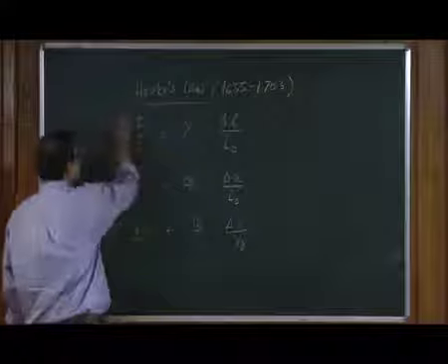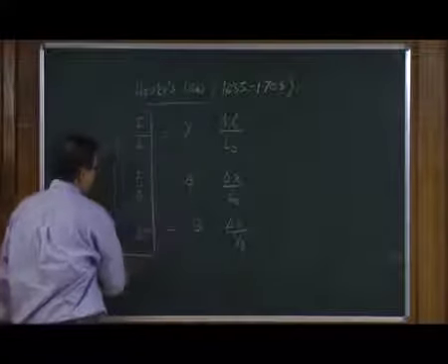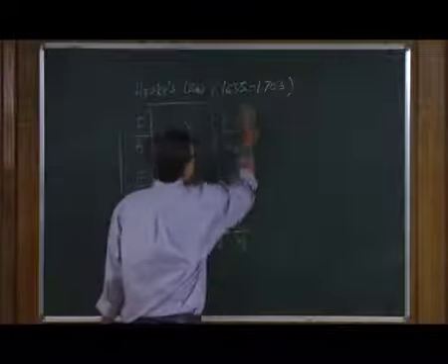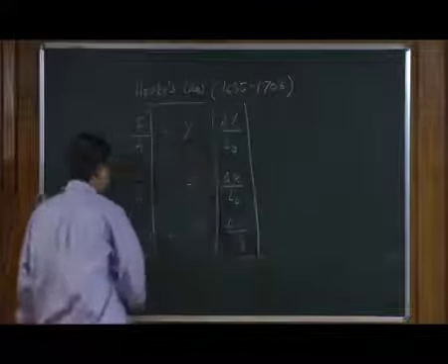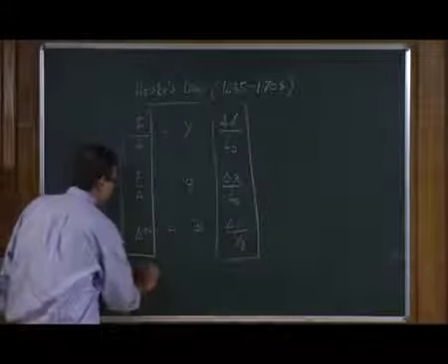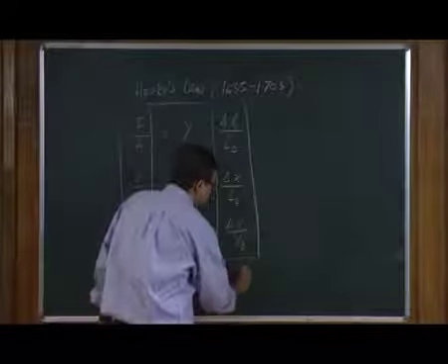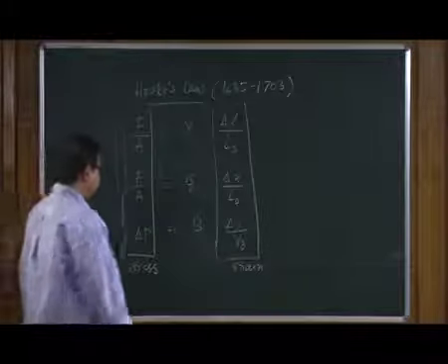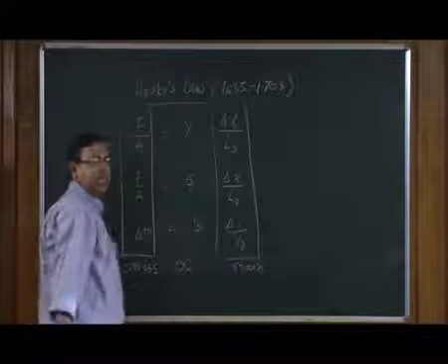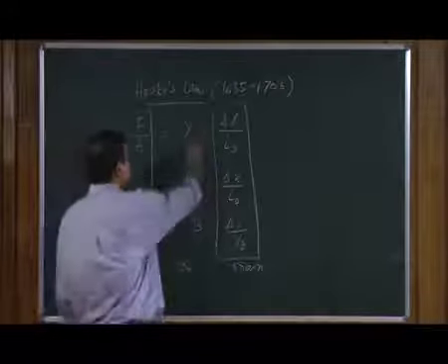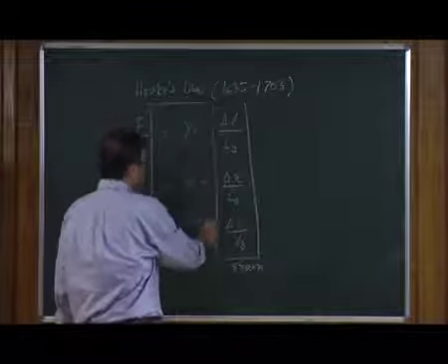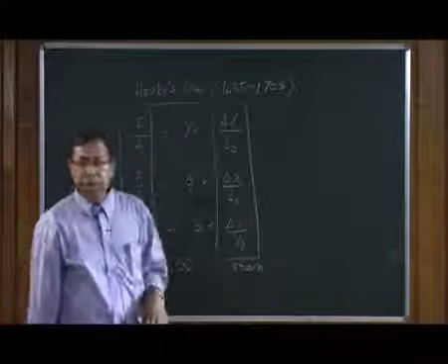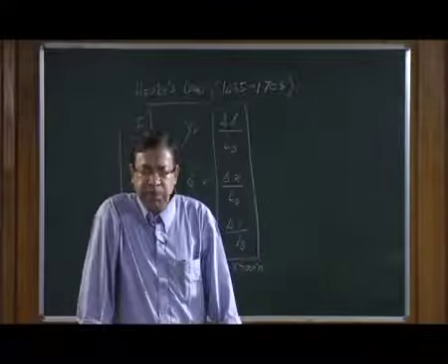Now, as you can see, on the left hand side all these are stresses, and on the right hand side all these are strains. So there is a stress and this is strain, and in each one of them the stress is actually proportional to the strain, where the proportionality constants Y, G and B are called Young's modulus, shear modulus and the bulk modulus, which depend upon the properties of the material.